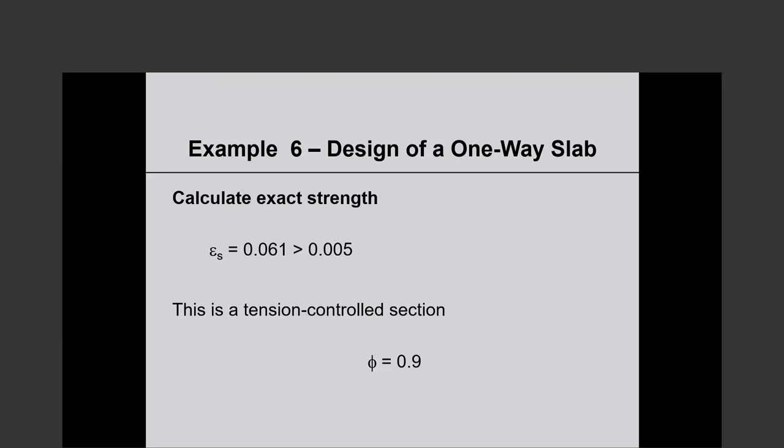It was 3,700. So let me try to understand. That made the beam over reinforced. You are going by the old rule of 3/4 of rho balanced, and the rho balanced changed. I'm just trying to understand.